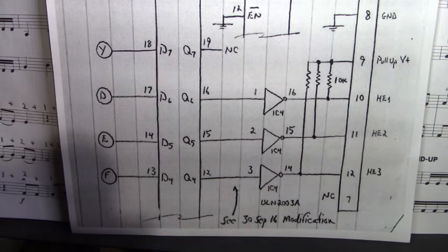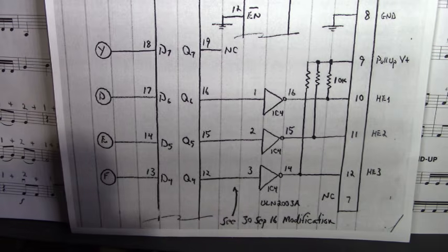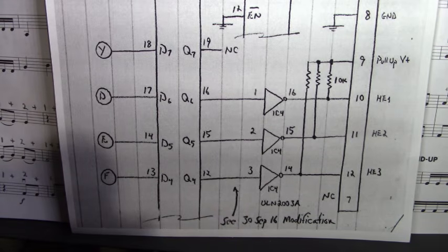Now this is a different Phoenix connector. The incremental encoder outputs are on Phoenix connector P6. The Hall effect outputs are on Phoenix connector P5. Also, the AM26LS31 and the 74HCT374 are separate ICs between the encoder outputs and the Hall effect outputs.